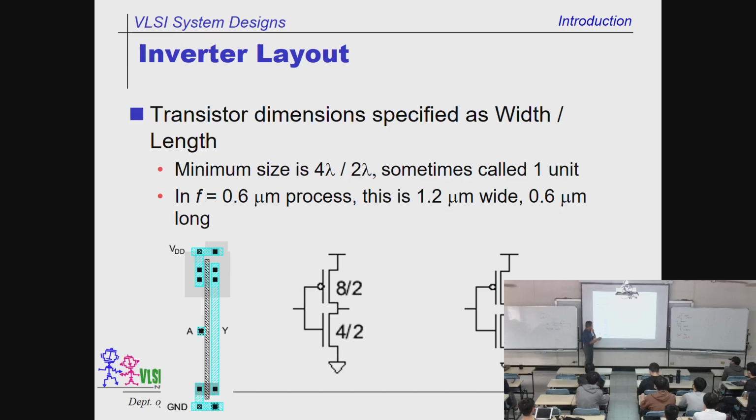So apparently these two transistors have the same length, but different width. Why is that? Everybody has the same length because we use the same strip of polysilicon. So basically, we understand that the signal, no matter whether it travels on the top or the bottom, goes through the same length. But how come the different widths?